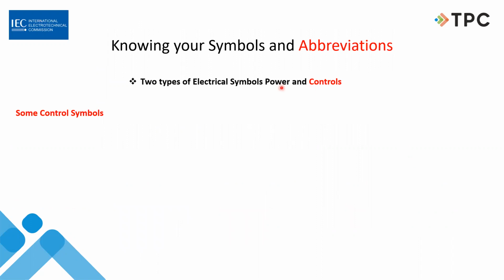Now we're going to talk about some control devices, not all of them, of course, because we don't have time to talk about all of them, but maybe some of the ones that we see on a more regular basis. This here is just a normally open contact, but because it has this little symbol right here and a dotted line, it tells us that somebody's going to do something to this contact. This is just not a contact on a motor starter or on a relay or something. This is special. Okay. So one thing we know right away is that it's normally open.